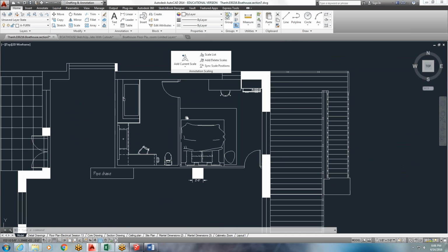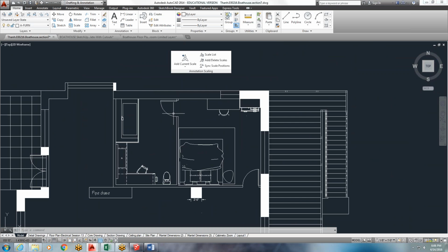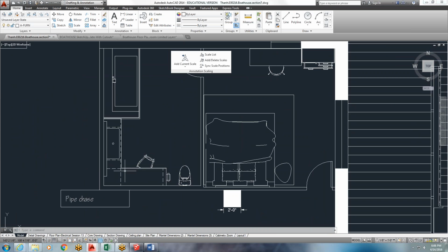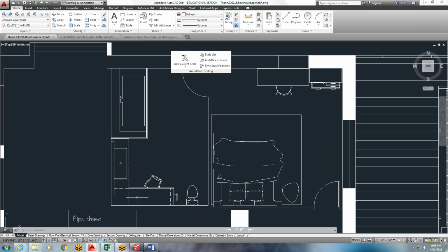Same thing up here. You're going to have whatever floor plan you had for your master bedroom, and this is where you're going to want to actually choose how your door is oriented. Now notice my bathroom layout. So for those of you who want to copy my bathroom layout in, you'll simply come out 4 inches and draw your door going in. And then you can use my layout, which I've supplied as a block in the drawing attached to the submission link. If you've changed it a little bit, then you could even explode my block and move it.